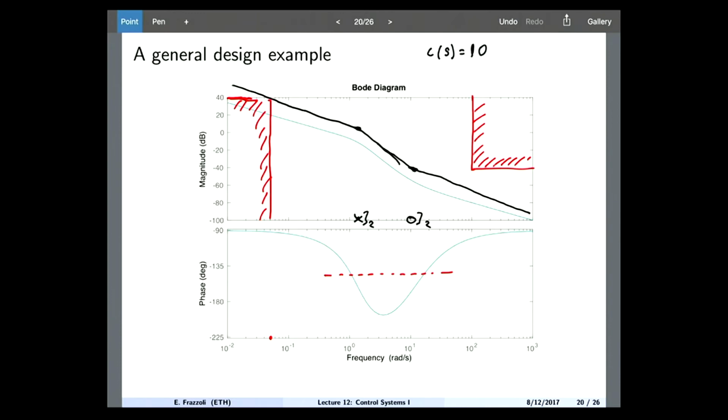Okay, fine. So what we need is to center this pole and zero around this point, right? And what is this point? It's probably 2 radians per second, roughly. How would you choose the pole and zero? They must be centered at 2, right? So let's say multiply by 5 and divide by 5. Maybe enough, maybe not.